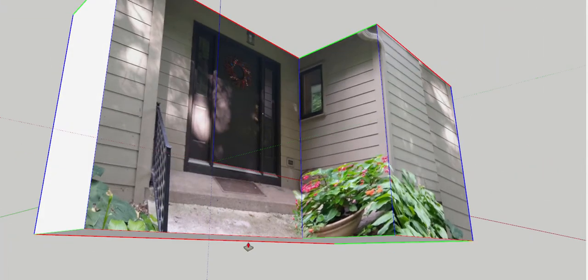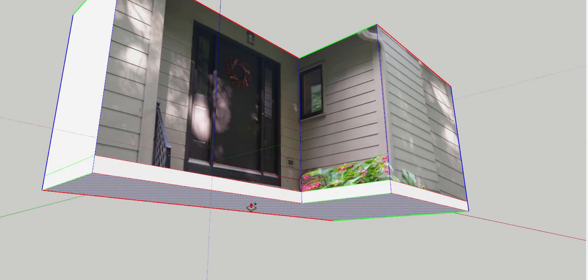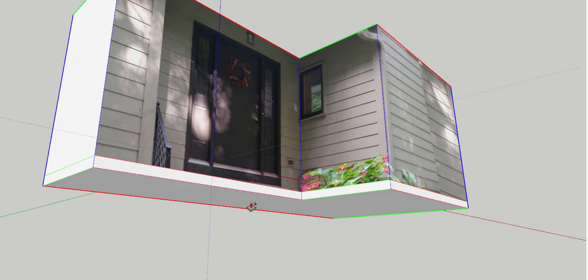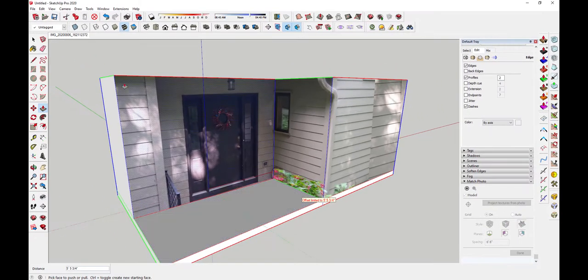I'm going to go ahead and push-pull this up to that bottom of the wall there at that point. Tap the control key, control push-pull down. I took a measurement. It's 5.5 inches. So I know that's 5.5 inches from the door. That step down is 5.5 inches, and this is another 5.5 inches to the ground itself. So I'll move this out to here right now.